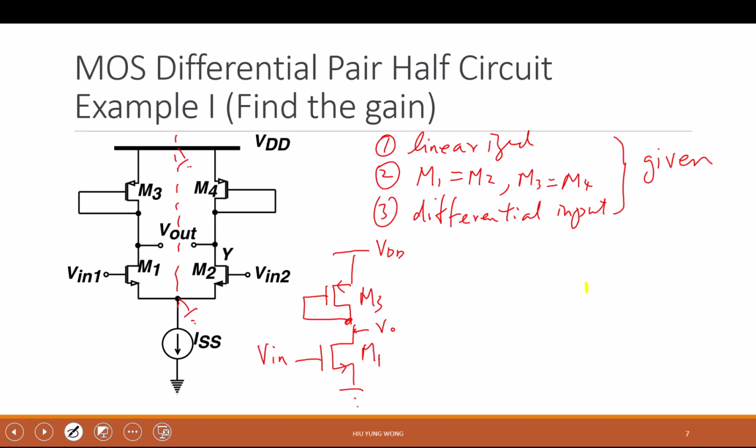First, the one on top is diode connected. Very good. The one on top is PMOS, right? So let me label them. This is source because PMOS has a higher potential at the source, right? This is drain, this is gate, and the gate is connected to the drain. So yes, you're right. This is diode connected, so it's just like a resistor.